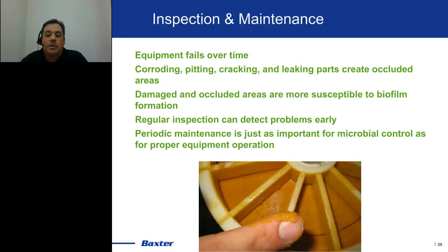There is always the chance, and I fully expect this is happening unfortunately across many industries, where you have a repair person that is opening up a piece of equipment, let's say a pump, for maintenance, and they see a slime that's growing in there, but they don't really think twice about it because they're there to fix whatever problem it is. They fix the problem and they put that pump right back into use. Well, of course, they're putting that microbial contamination right back into the system.